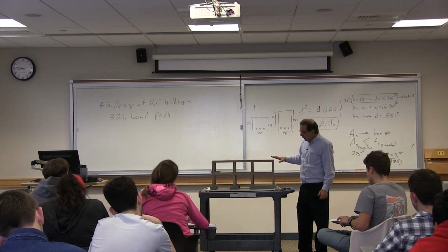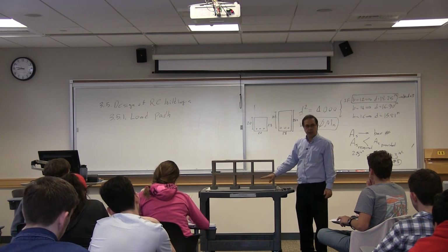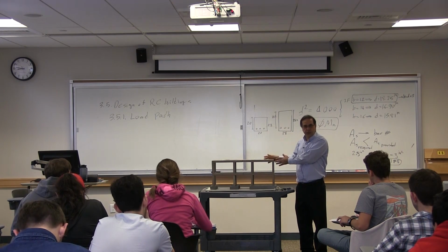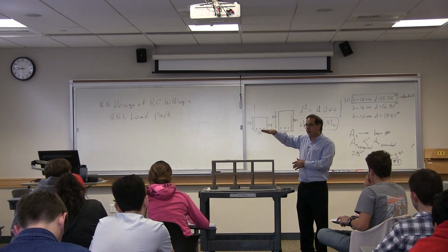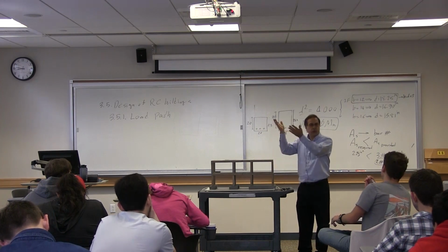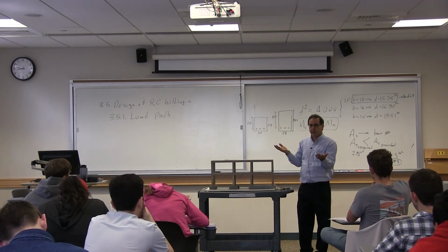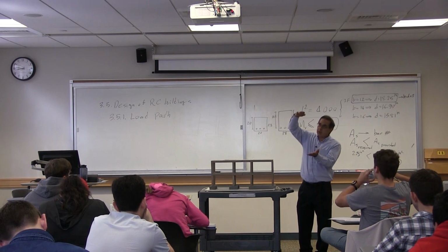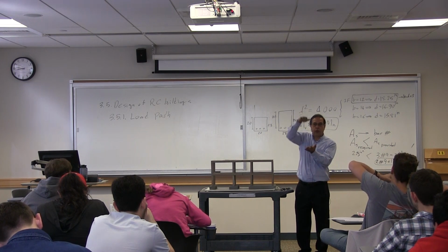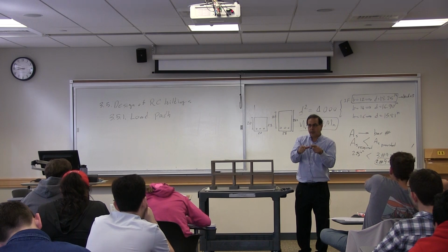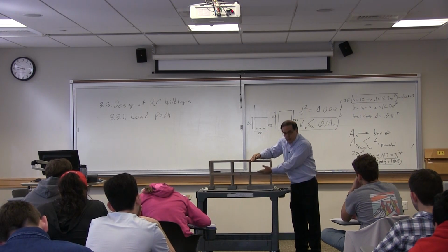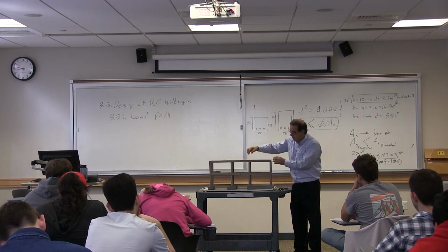In other words, if I have a building like this, 2-story or 100-story, same geometry, and I'm looking at gravity loads, the beams for all stories are almost the same. That means the loads from higher floors are not going to transfer to the lower floors; they are going to transfer through the columns. It doesn't go to the beams, with some approximation.